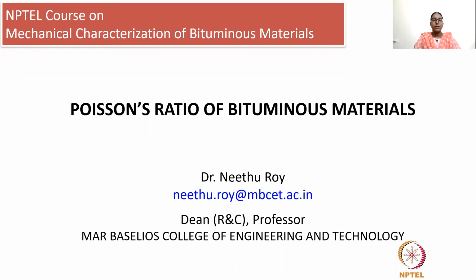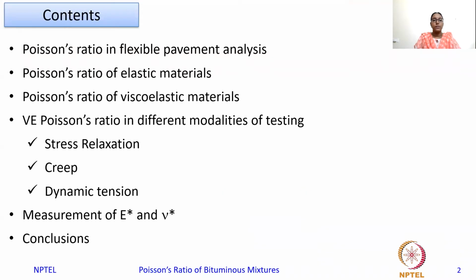Hello everyone. In this lecture, we will discuss Poisson's ratio of bituminous materials. This is the outline of this lecture. We will see what is Poisson's ratio for elastic materials, then Poisson's ratio for viscoelastic materials. The viscoelastic Poisson's ratio in different modalities of testing such as stress relaxation, creep and recovery, dynamic tension, etc. And then we will see the measurement of a complex modulus and a complex Poisson's ratio.